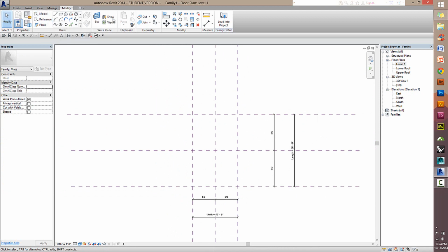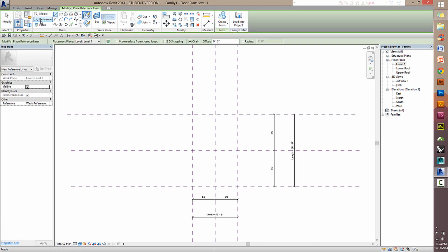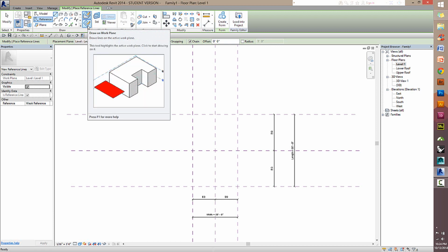Then I'm going to select the type of line I'm going to use, and it's very important that when you do this, you keep a very rigid order. First, you select what type of line of these three you want to use. Then you select which of these drawing types you want to use, and I'm going to draw with lines. Then you select Draw on Face or Draw on Work Plane. This is a very critical part of the drawing process and will determine whether or not your line work follows reference planes or other geometry that it's associated with when those geometry move as their parameters shift.